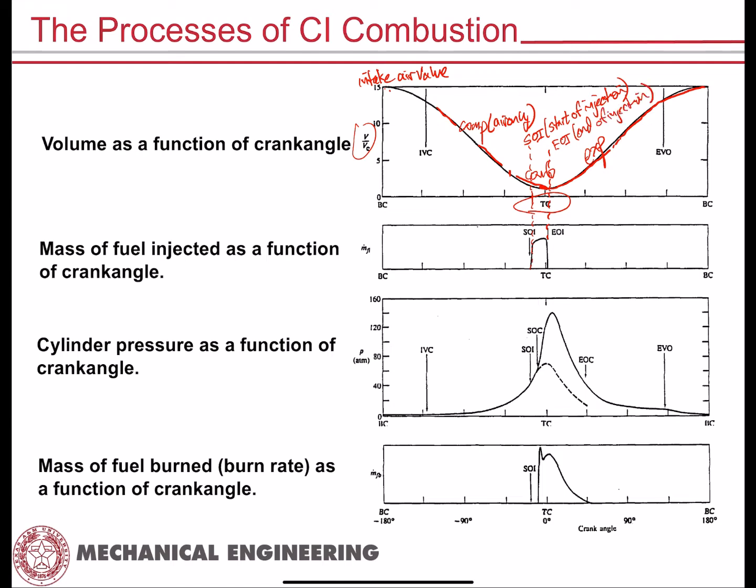Now, there's a lot that happens after start of injection. We're going to talk about that on the next slide, so I'm not going to spend too much time on it. But basically, in short, there's what we call an ignition delay period. The ignition delay period is just that time from when you start injecting the fuel to when you start combusting the fuel.